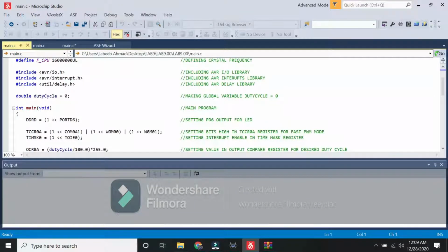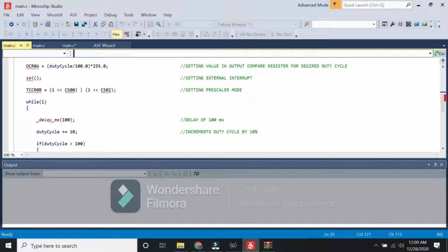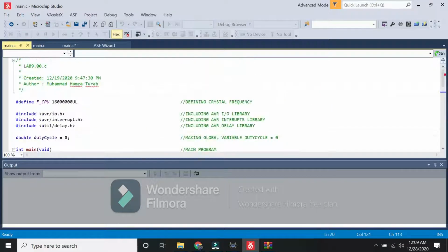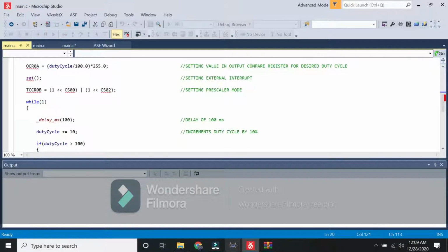In the code, you can see that first we are initializing the PWM mode for accuracy and more precision. With PWM we can control the speed of DC motors and many other things. If we don't use that command, our line follower stops abruptly, cannot make sharp turns, or does not work smoothly. Same here, that is why we are using it.